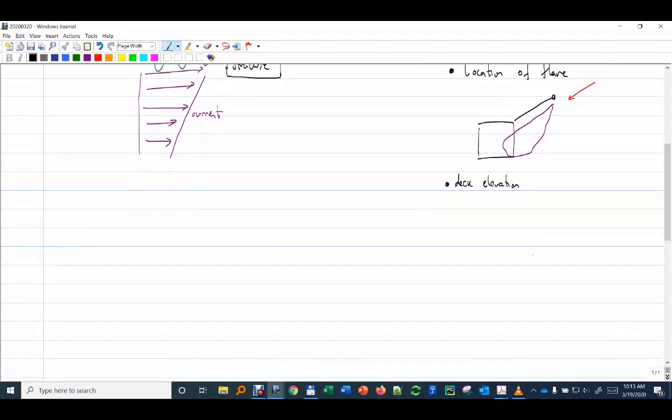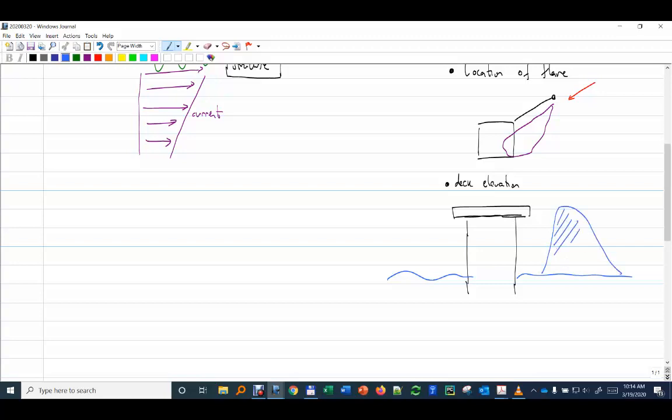Okay, and that's related to if we have, for example, a spar. Let's use a spar as our example. And we have our sea level here. We want that the most critical wave, or the biggest wave we can have, and that's usually estimated over a lapse of 100 years, doesn't reach the deck. We make the deck high enough such that this wave cannot reach it. So that's what we call the 100-year wave.